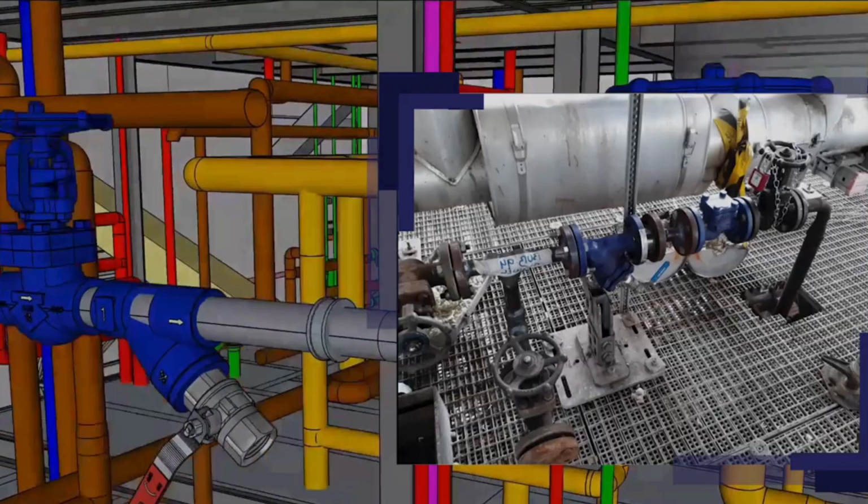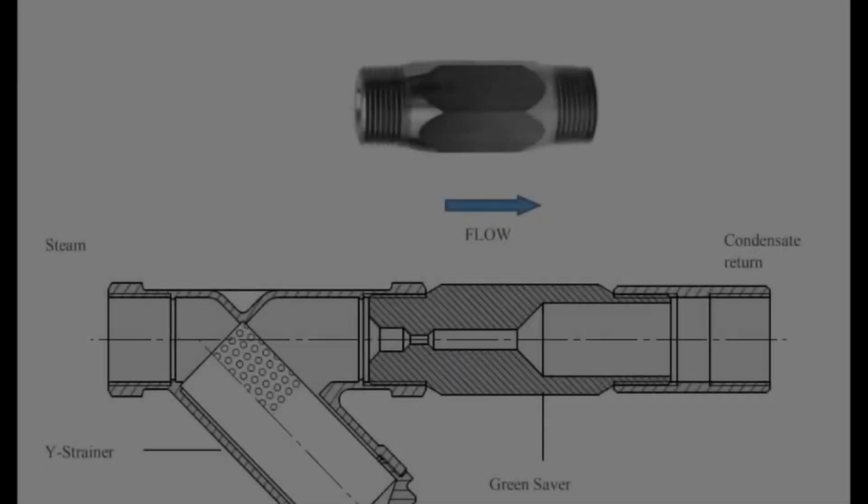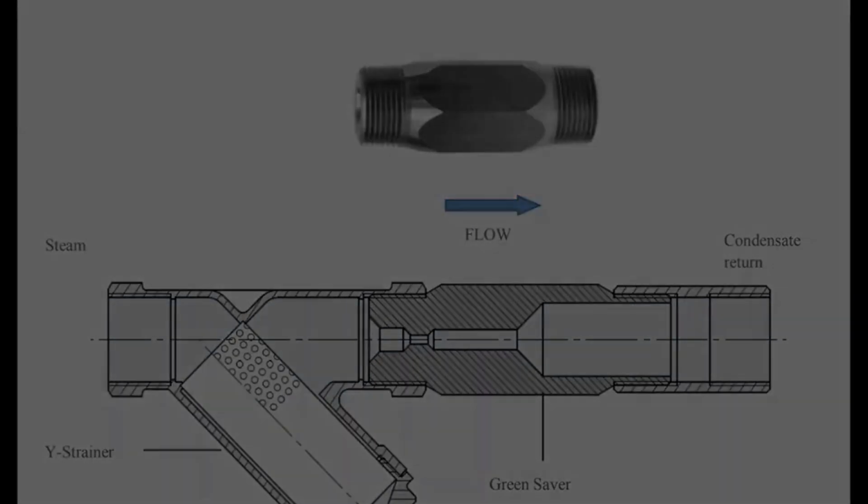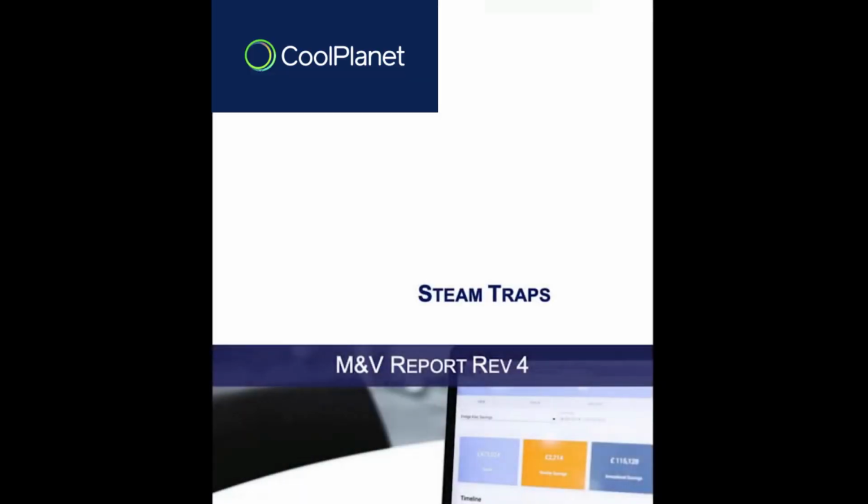Lastly, on the hex, as with all the steam users on site, the mechanical steam trap was removed and a Venturi trap was installed along with a bypass circuit for easy maintenance. Most importantly, a blowdown valve was installed on the Y strainer protecting the Venturi steam trap. We find that on the majority of sites, the steam system may be suffering from corrosion, wear and tear. To help keep the system clean and increase performance on indirect steam users, a maintenance schedule around blowing down these strainers will dramatically increase efficiency after a couple of months. This maintenance frequency can be reduced as the system becomes cleaner.